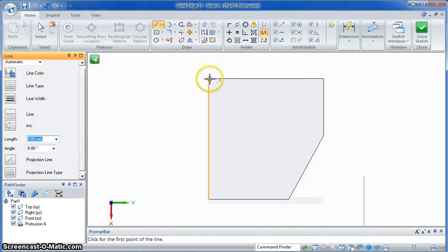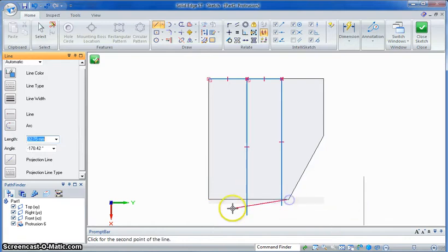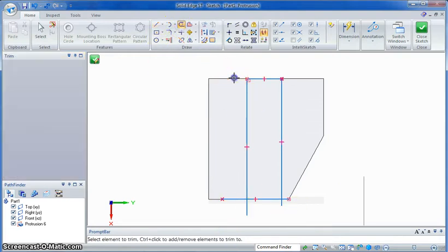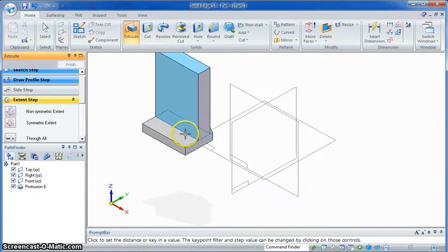Okay, we're going to start with a few construction lines. So off the corner, we're going to go 22 in. We're going to come straight down, and we're going to come across here, another 20. There's always more than one way to do these things. There's no absolute correct way. I'm going to start with that point and just cross over there without even measuring. Now I've got some extra lines sticking off. I can use the trim tool again to get rid of those extra lines to make my shape. If I hit close sketch, they should all know they're joined.